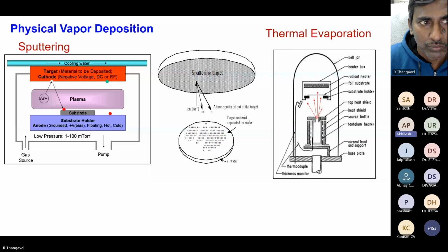And planarization: a flat surface is highly desirable for subsequent lithography and etching. CMP, chemical mechanical polishing, is used to planarize each layer of dielectric in the interconnect system, and it can be used in the front end process.